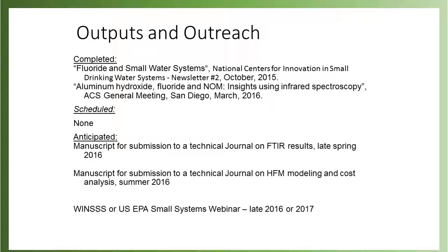If you are getting some electrolysis, you could be creating some assimilable organic carbon in there, so you might increase some biofouling potential in the RO. But that stream doesn't go in the RO, so it's not going to be a problem. There really are 3 streams. There's the electrode rinse stream, which is really separate and a tiny fraction, and then there's the treatment stream, which gets separated into dilute and concentrate, and those are the things that go on.